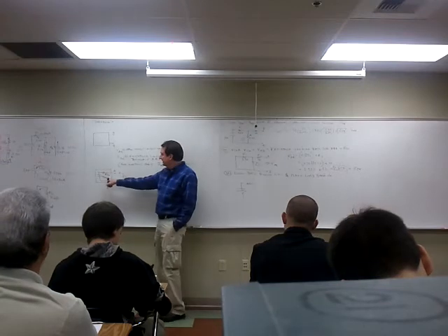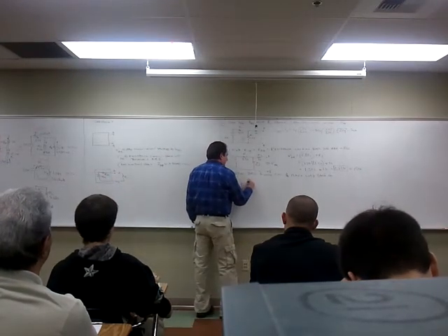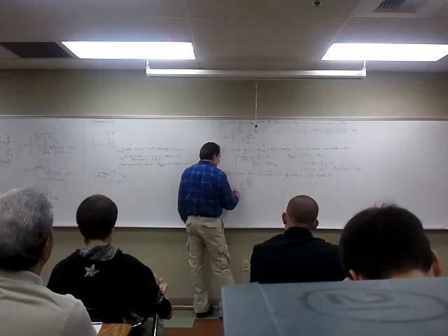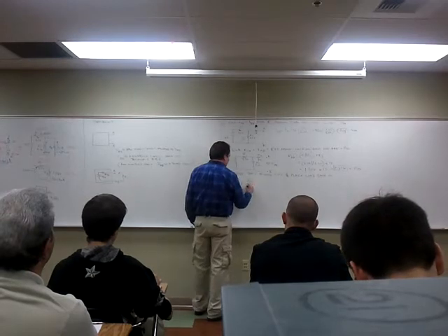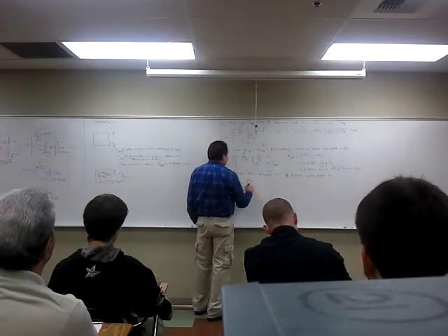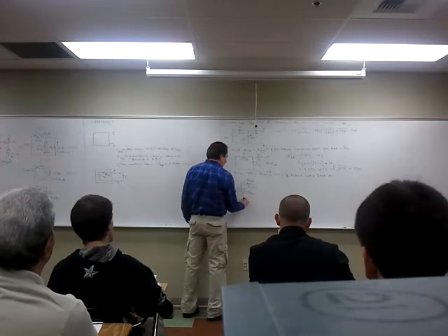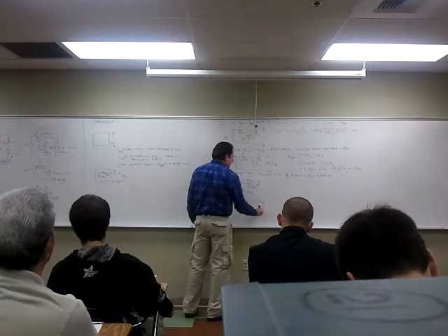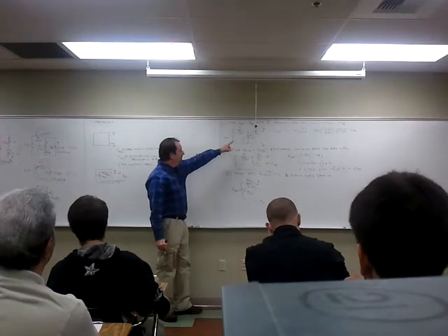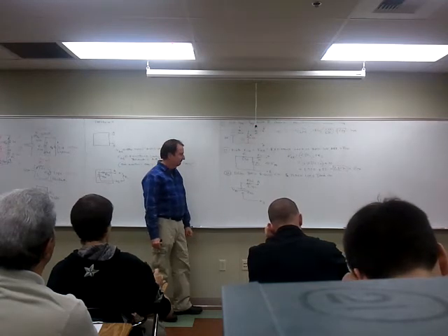It is always this. This is our Thevenin. This is V Thevenin. Our Thevenin is 2.32K. V Thevenin is 20 volts. And this is terminal A and terminal B. And notice that A was more positive than B, so I show this source in the proper direction.